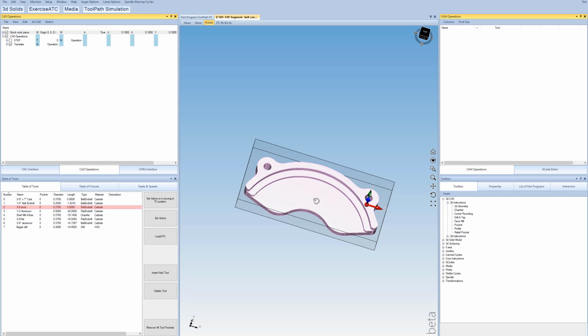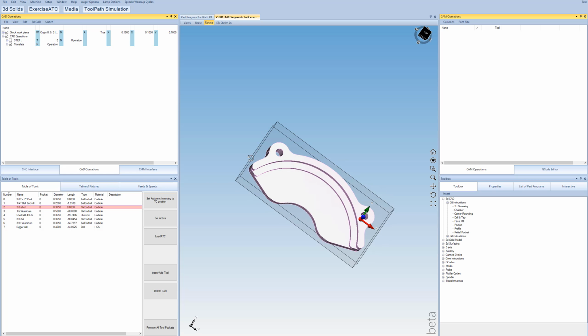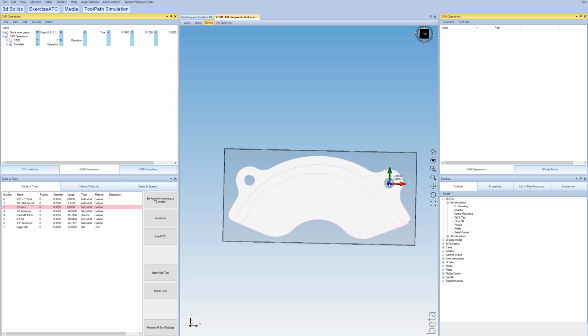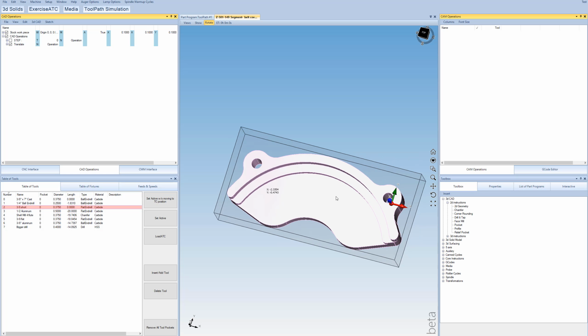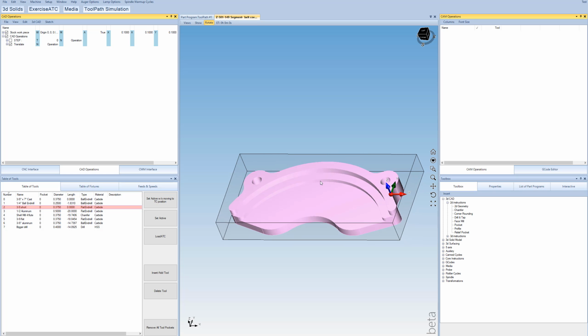So the first operation would be something like you just mill flat one side of this, and then you drill two holes here that are exactly this diameter, or you could circular interpolate them, and then this entire block just fits onto the fixture that we just made. Okay, and then once you do that, you have to be conscious that you're going to have washers and a bolt up here on both sides that are holding this block to the fixture. But there's no reason for us to have to cut this surface again, because we've already cut that in the previous operation in the vise.